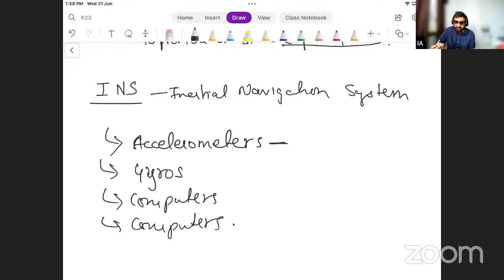With respect to time, we then use data from the accelerometer to give us velocity. And it is all based upon the sensitive movements of the accelerometers. What is the displacement from their initial fixed position with respect to going up, going ahead, or going down? So, in order to get linear forward acceleration, north-south, we have one accelerometer going north-south. And then to check lateral acceleration, or east-west acceleration, we have another accelerometer.